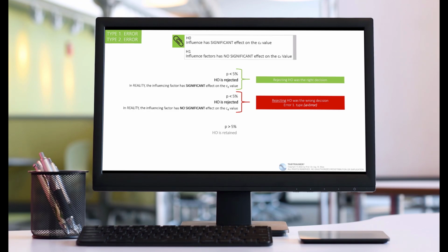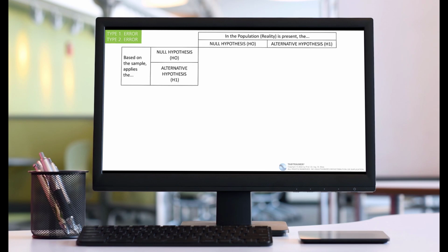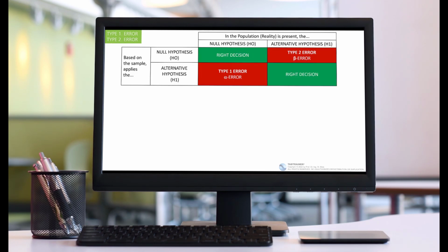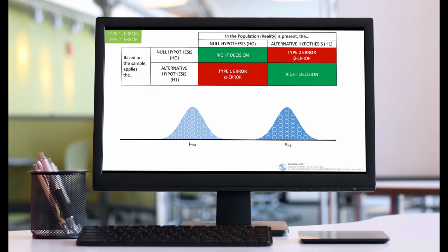To determine the air resistance, the respective skateboard pilot in the racing suit is exposed to a defined airflow in the wind tunnel, and the drag coefficient, the so-called CD value, is measured as a measure of the aerodynamic behavior of the racing suit. The lower the CD value, the lower the aerodynamic drag, which in turn has a positive effect on the maximum achievable speed.